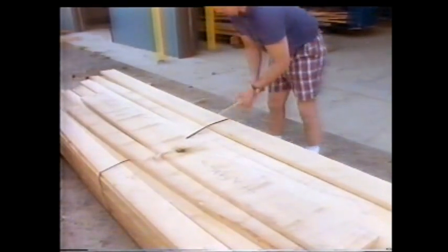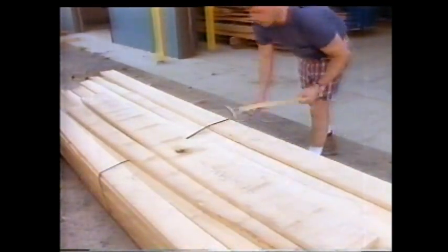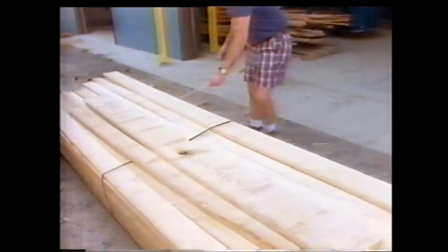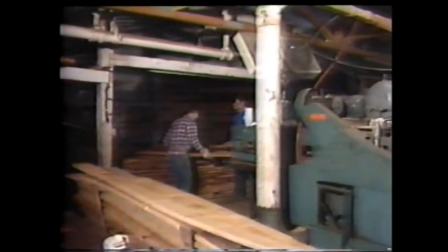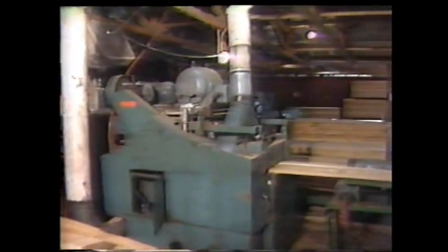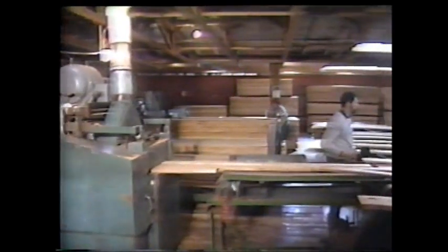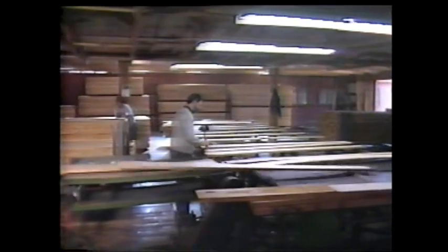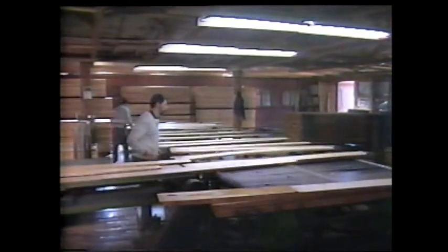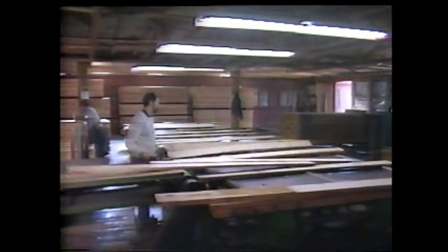In this illustration, the inspector is marking the board so we can visualize what is going on. In actual practice, this is done in the head of the inspector. Two boards that are exactly the same size with the same number of cuttings and the same amount of defect-free surface area could end up with different grades because the location of the defects could prevent a board from having large enough clear cuttings to make the higher grade. The figures are calculated.